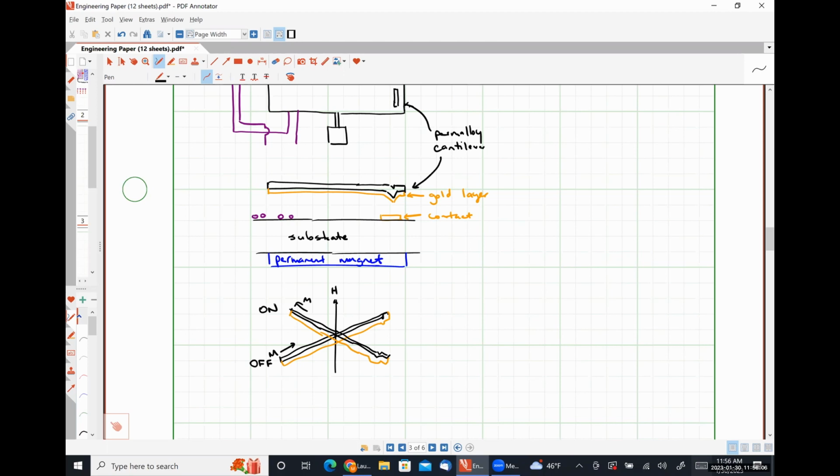And it's got a hybrid drive system effectively. So it uses not only the permanent magnet, but also the coil. So effectively the coil is what's used to reverse the magnetization vector of the cantilever, causing it to go from one state to the other. And what's very interesting about this is it's bistable, meaning it has latching, okay?